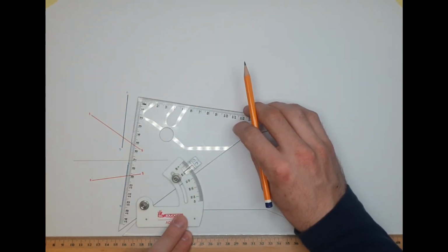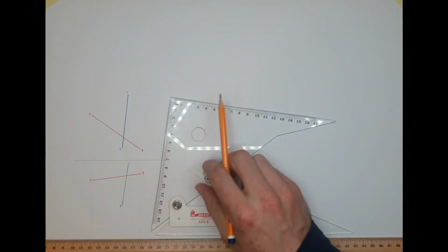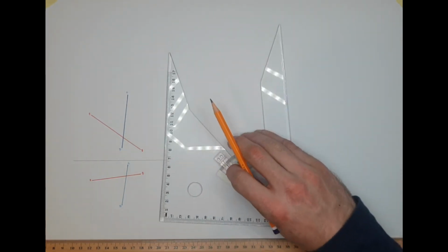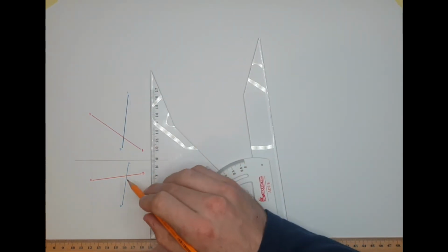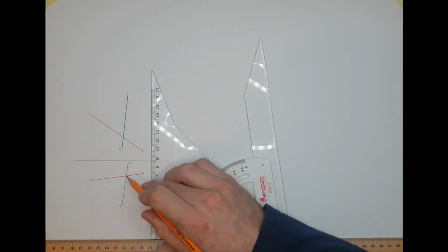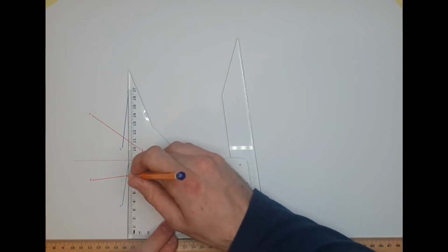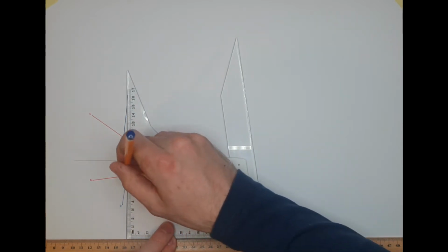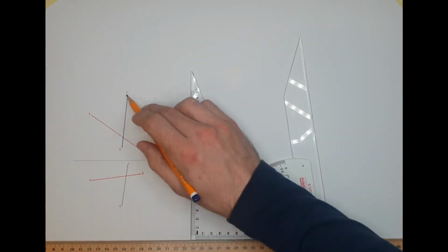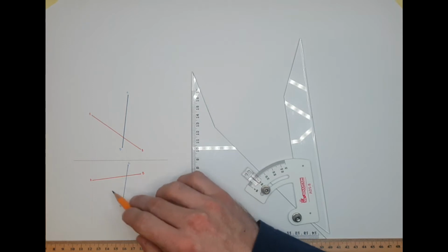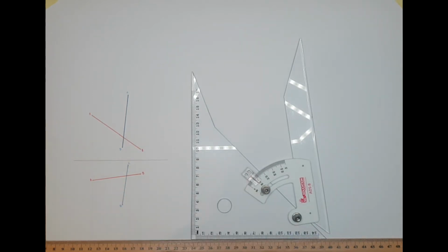So one thing we need to be absolutely certain of here, and we just need to understand this. If you're setting up the question yourself at home, the point where they appear to cross in each view, obviously if they're skew lines, those points cannot line up. Because if those 2 points where they appear to cross in one view and in the other view line up, then that means you have just drawn intersecting lines, not skew lines.